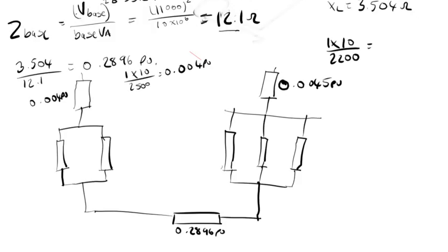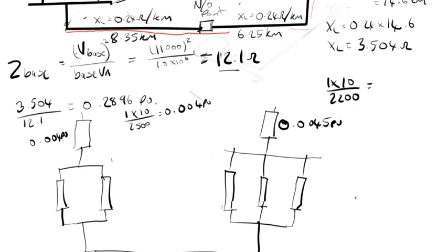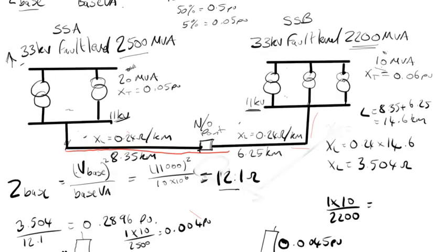Because we use this 10 MVA figure here, the bases stayed the same for these 3 transformers. So basically the reactance in per unit values shown here is the same as the one down here, because it's the same base, so that's 0.06 pu all the way through for all these, and 0.06 pu there.